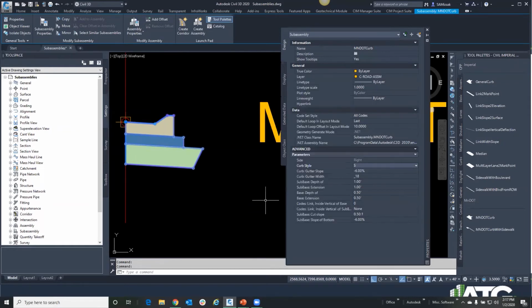And then S. What this does is it takes predetermined values, so now that user doesn't have to come in and say, oh, I need B612, so my gutter width needs to be 12 inches, my top of curb needs to be 6. I just come in and I set everything up to do B style curb. Now this is set up to be default 6-inch curb. It's not that common to have 4-inch curb up here, so it's usually always 6-inch. So we went with B612, D 6-inch, V and S on there.